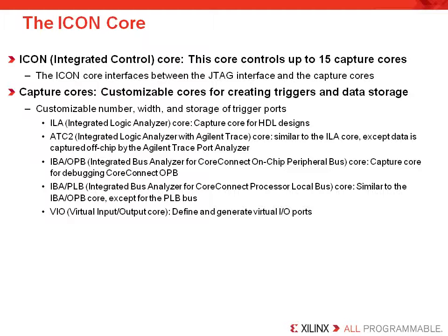The integrated bus analyzer core has two versions, one for the OPB and another for the PLB bus. These are embedded buses that are frequently used by our customers using our Embedded Development Kit, or EDK, targeting either the MicroBlaze soft processor core or the dedicated PowerPC available in some of our device families. These are especially helpful to users debugging the behavior of custom peripherals attached to either the PLB or OPB bus. The VIO core, as mentioned earlier, is used to define and generate virtual I/O ports.